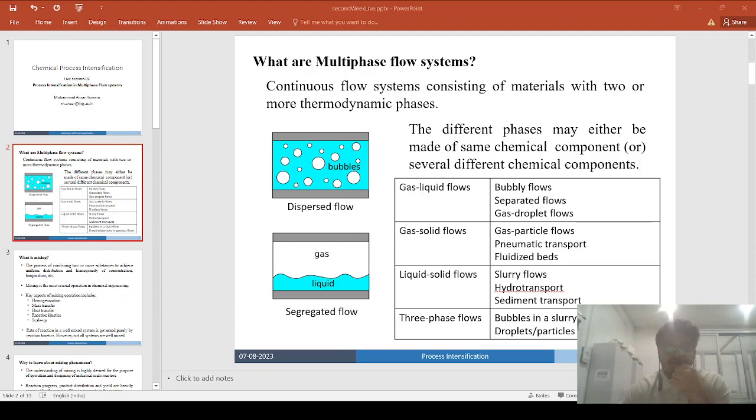Now in the previous session, also in the previous week, the topics discussed were that process intensification can also be done by combining two different processes. Like if there are two different process stages, a reaction stage, after performing the reaction you will get the product, the yield, and that yield would contain the product in combination with the byproduct. Then comes the separation stage, where you separate the product from the byproduct. So what about if you combine both the reaction and the separation stages together to make a reactive separation stage?